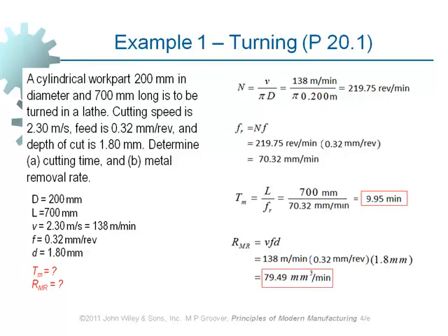Because spindle speed is different on different machines. You've got different machine tools, you've got different spindle speeds. But cutting speed always can be decided on the basis of spindle speeds available. Some other thing that we've got to take into consideration in this problem is the spindle speed which we have computed. What is it? About 220, right? About 220, not exactly.